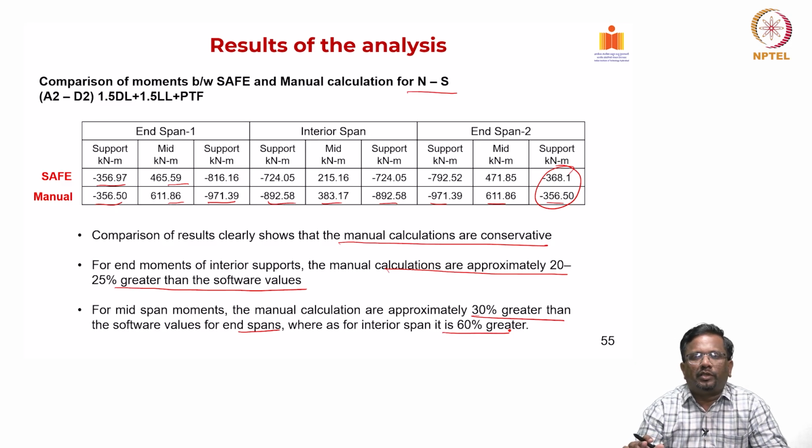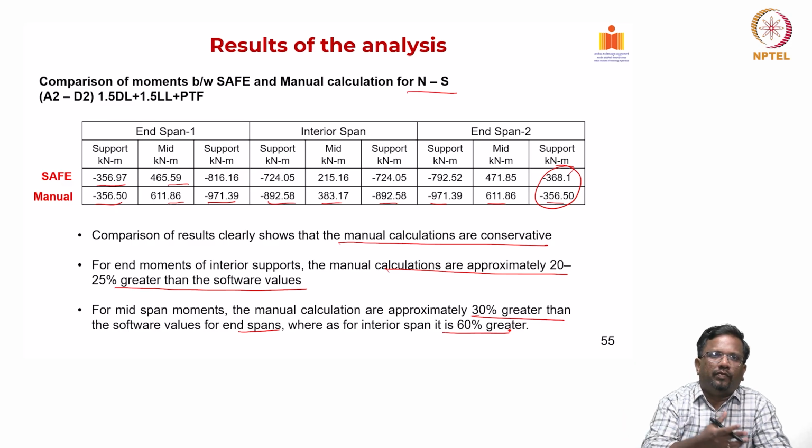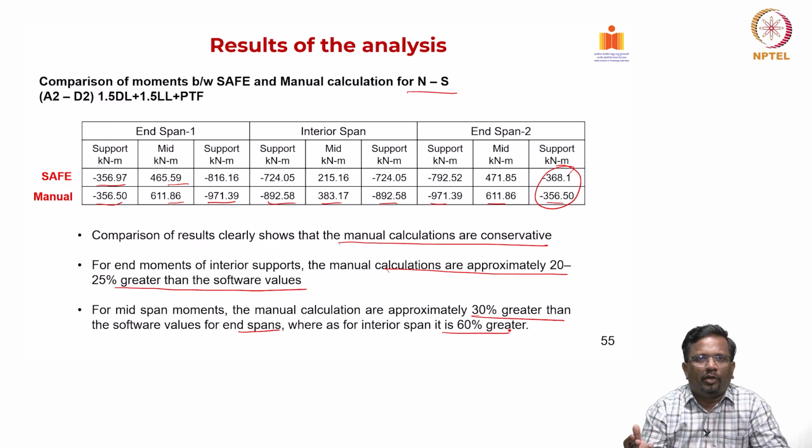But having said that, it is always a good practice to have an Excel sheet developed for very common scenarios so that you can quickly check whether the number that you are getting from your software is making sense or not. Otherwise, you can have very erroneous results depending upon the assumptions that you model and how you model it in a commercial package. You can always go back and check what is the number of cables that the software is asking vis-a-vis what you are getting from your manual calculations. Very important for us to check.